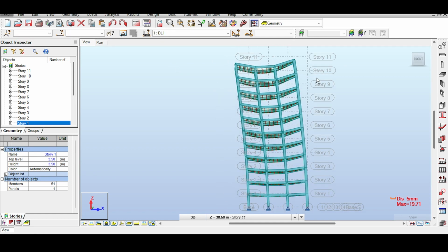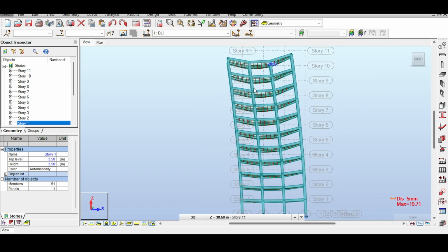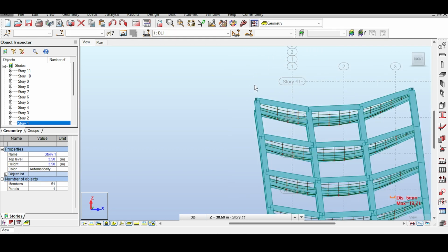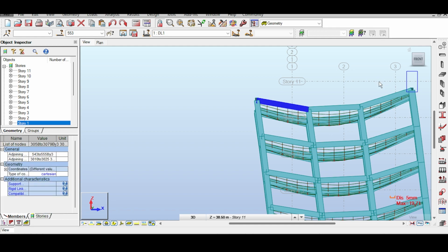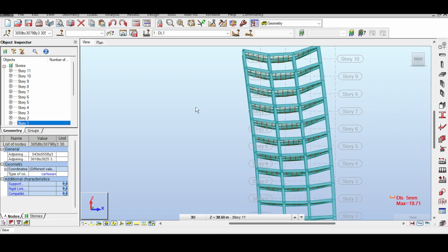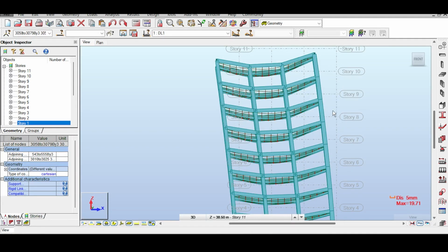Why is that? A quick explanation that still needs to be further elaborated is that your vertical load-carrying elements on the left side have a weaker stiffness than the load-carrying elements on the right side, which means that the left side goes down more than the right side. Look at this. The deflection of the left side down is more than the deflection of the right side down. This causes a tilt in the structure, which makes it tilt towards the weaker elements. Now, the problem here is compound, because if the structure tilts, then suddenly, you have extra moments on the columns that were not accounted for because of the P delta effect if you want to do a second order analysis.